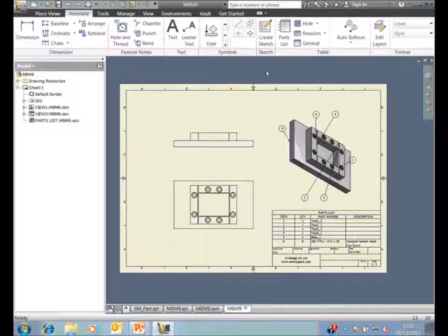So the whole idea of multi-body modelling is to get the idea across straight away, either as a single sketch or, as I've done in this case, a derived component, and then work off of that and use the functionality that you have in a part file of accessing dimensions in the part file, other edges, other faces in that part file, and to be able to model bodies very quickly that we can push out to an assembly later.